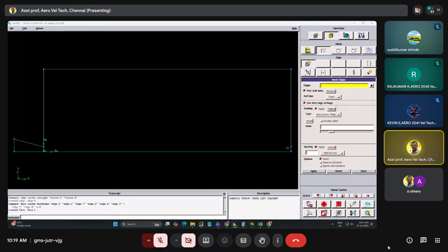The only thing is that you have to be very careful in meshing this one and this one. It should be the same. You just select interval count, showing 6, so you have to double it, 12. See here, mesh edges. I am doing mesh edges for the domain nozzle and nozzle inlet and domain exit at that particular nozzle inlet. It was default 6, so I am making it 12. Do right click, edge mesh will come.